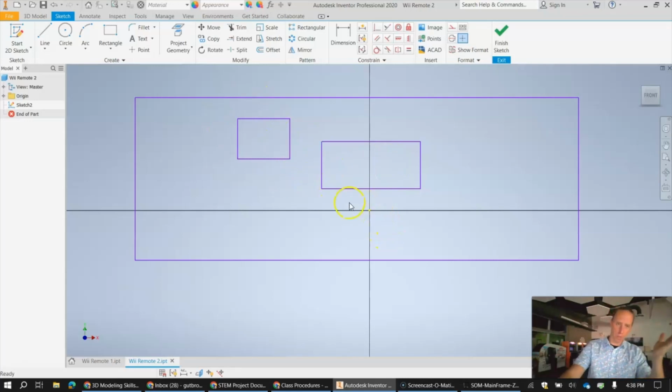There's a couple different ways we could do this. Of course, we could just click the back arrow, or I could push Control Z to undo. But I want you to understand some of the other ways of doing this kind of stuff, because you're not always going to be able to click that back arrow. So for example, if I want to delete this line, I'm going to left click release on that line. Notice how that highlighted a slightly different color. Now I'm going to press the delete key, boom. Watch that, just that line deleted. So you right now delete one of your lines.